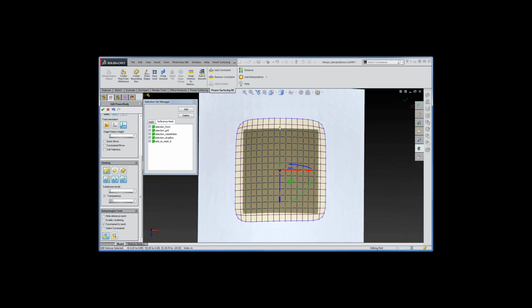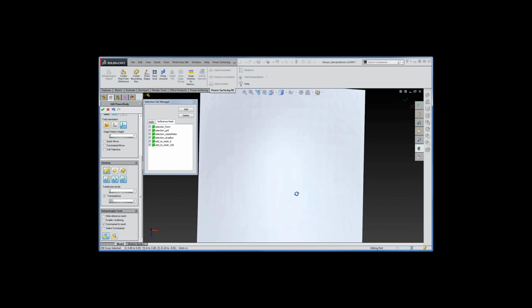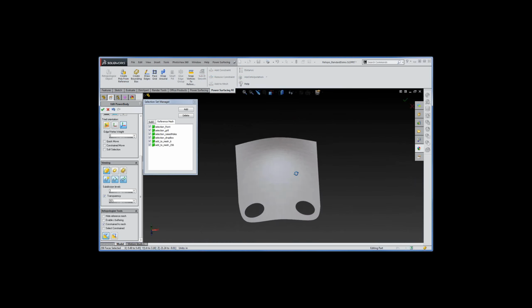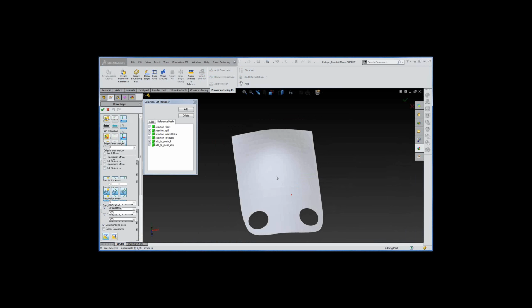or the other thing we can do is make a retopo reference mesh from any other piece of geometry. It doesn't have to be a scan piece, and I'll show you that really quickly in the next one I'm going to do. So tell this one to add mesh, and there we go, ready to start the retopo.